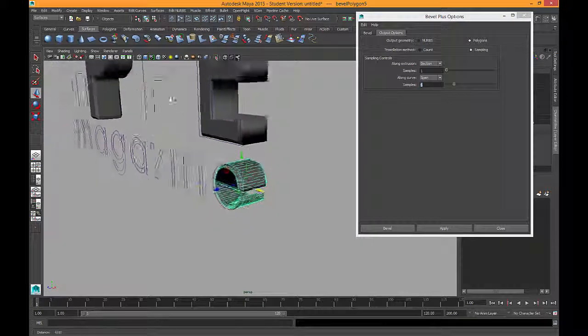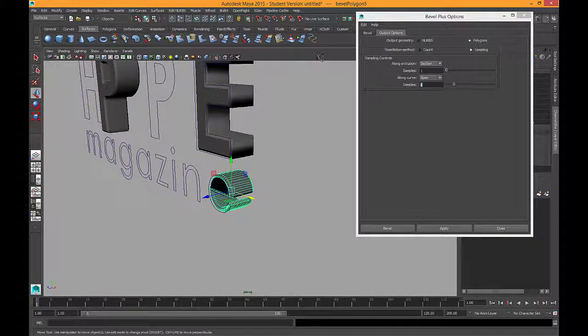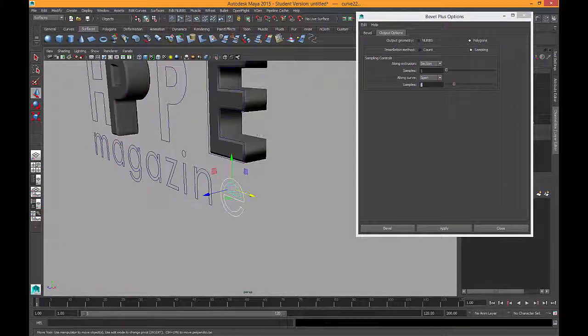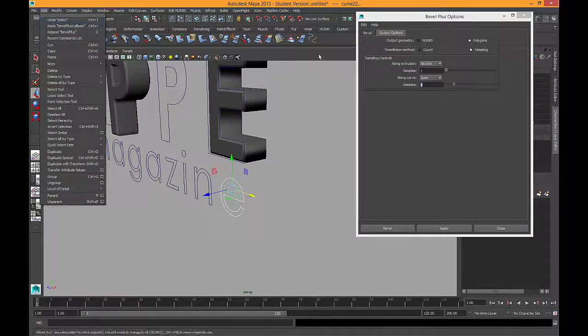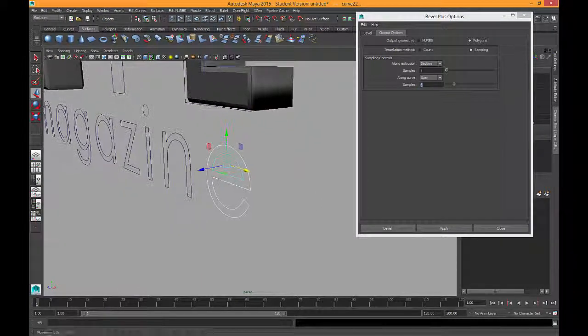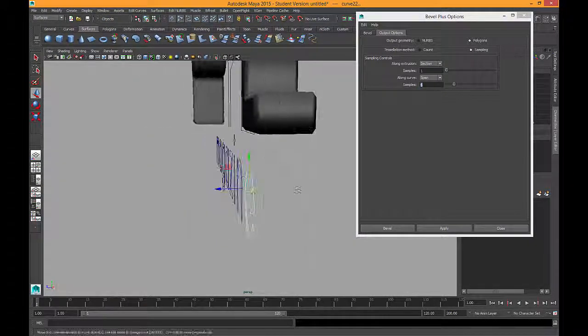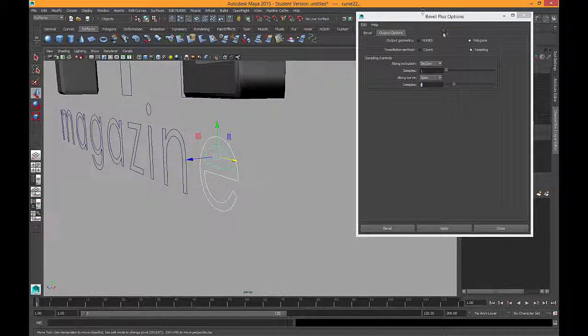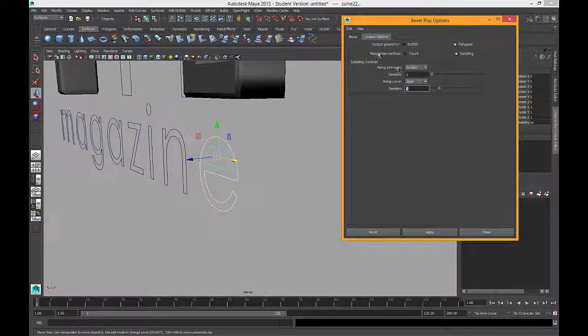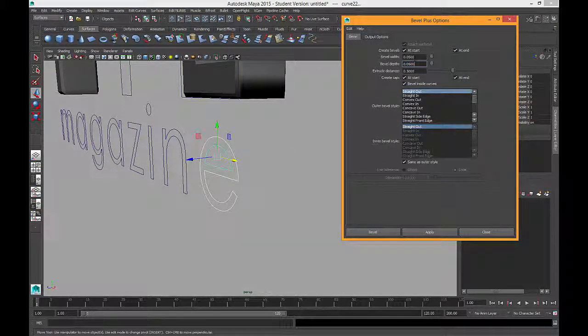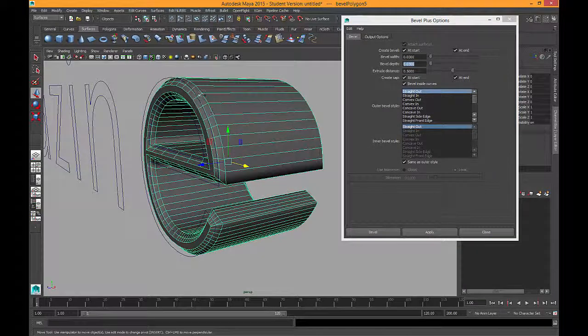so what we can do there, I'm just using undo as well, by the way. You just click here in the viewport border and just use edit undo. It should be pretty obvious that's what I'm doing at the moment, but just to mention it. So in that situation, I'd need to drop this down a little bit more. So I might go like 0.03, for example. And then apply that. You can see now I'm getting this nice bevel.